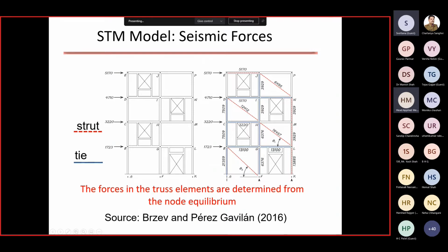So it is a rather complex modeling approach, and it is mostly intended, in the context of confined masonry, for when you have significant openings, unusual openings, which you cannot easily model with the wide column model. Because if you look at this wall, in this particular example, you would not be able to model it with the wide column model. Why?